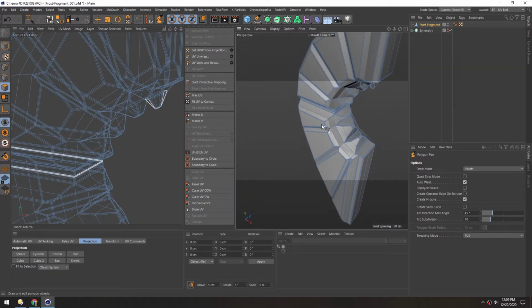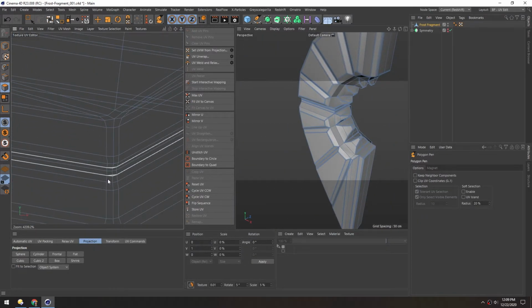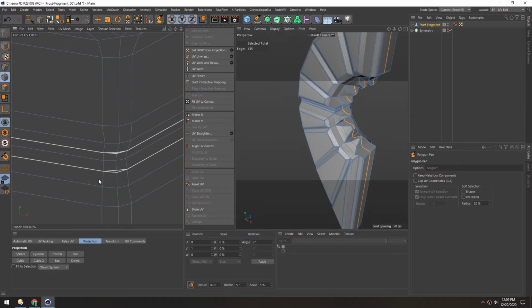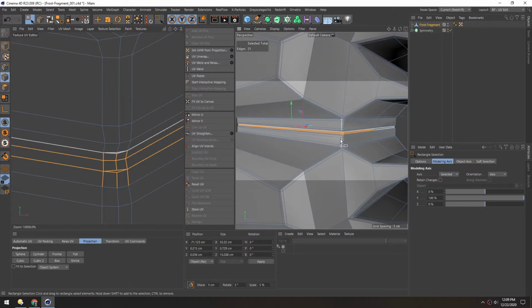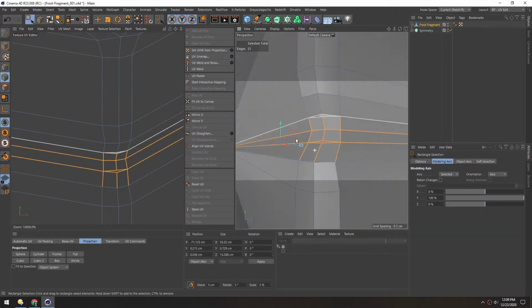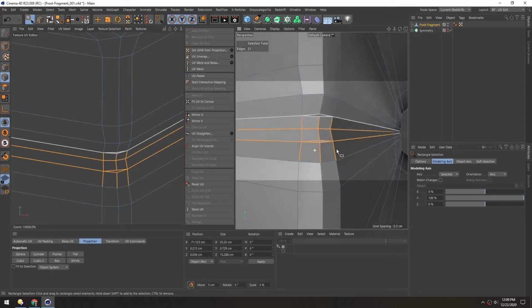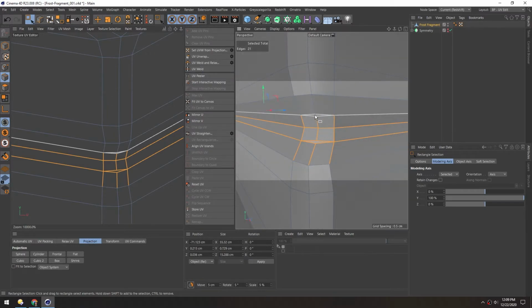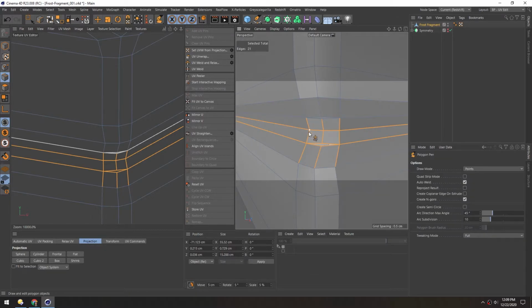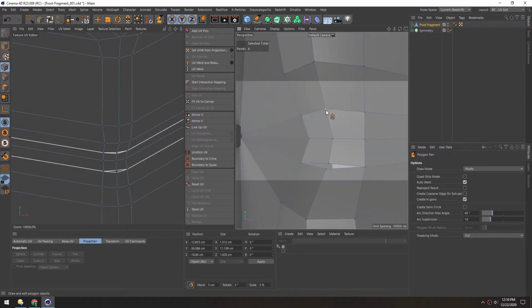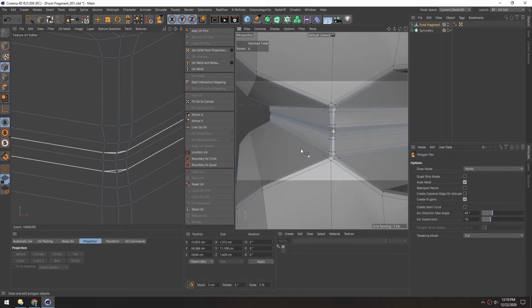Now the other piece is in here somewhere. So let's see what's going on. We did hit delete, so it probably deleted this inside polygon. So hitting ME to go back to the polygon pen tool, we'll go to point mode, and I'm just gonna fuse these together.